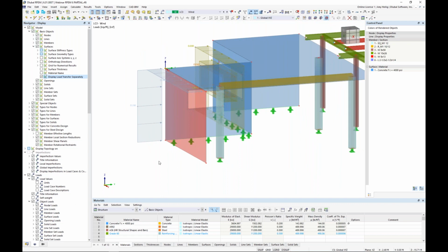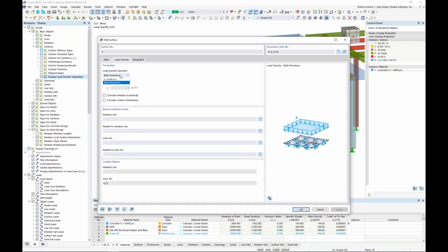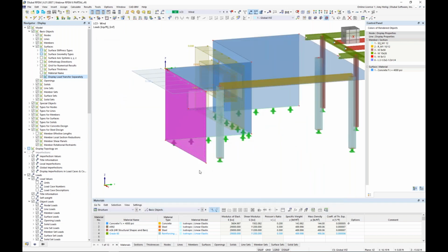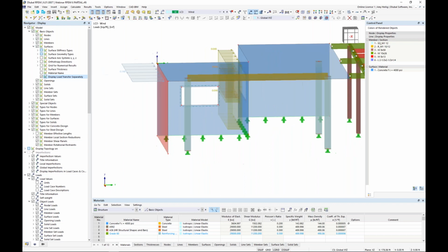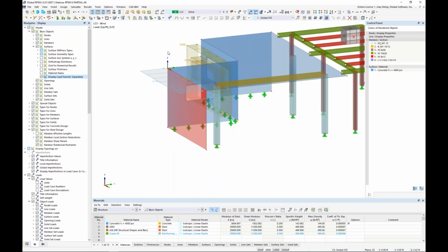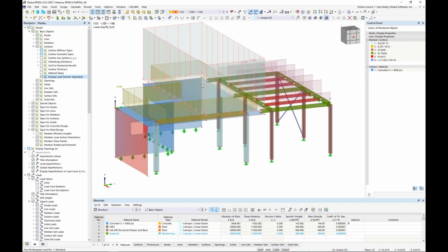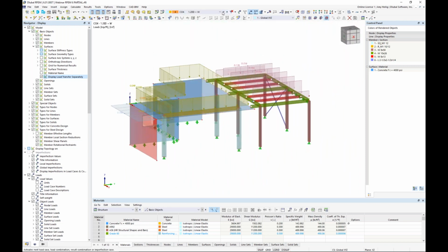And if we decide, well, I'd really like to have one-way area load distribution, no problem. Just double click on this surface. And remember, under the load transfer, let's change this to the local Y direction instead. And I click OK. So now we see a single line load kind of oriented here towards this top slab element. Okay, so now we have defined all of our various loads. We can view them displayed together for all of these different load combinations, considering the relevant load factors.